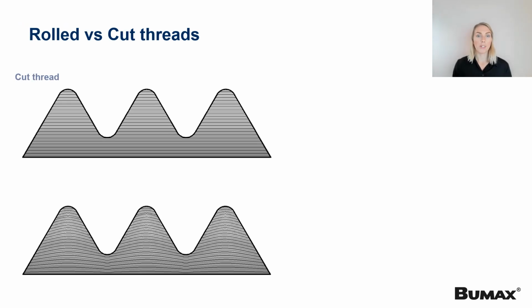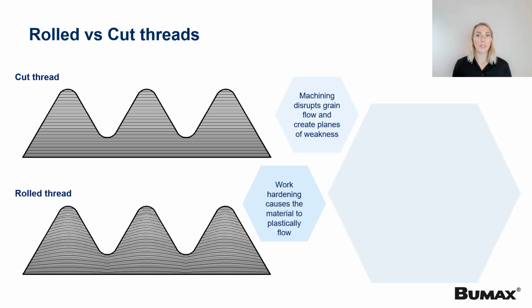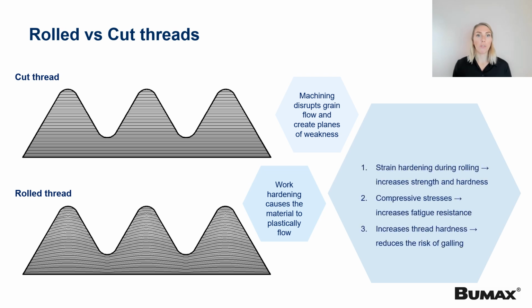Thread rolling has several advantages that traditional thread cutting processes lack. One key advantage is the strengthening force of the pressure, instead of cutting through the grain of the part's microstructure and weakening the workpiece itself. Thread rolling realigns the grains while leaving them largely intact.